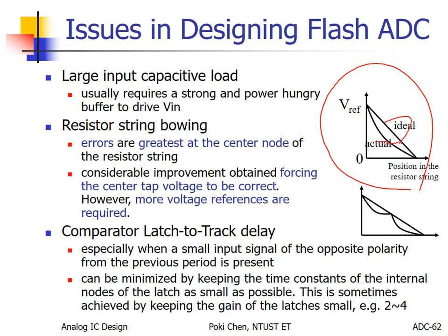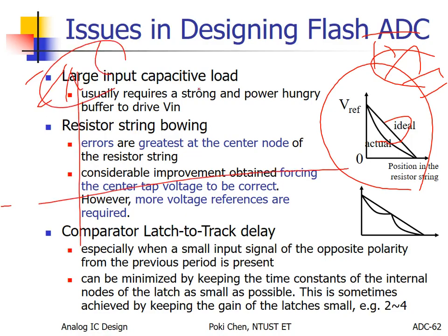If some of my students design an ADC or DAC, especially with a binary-weighted structure, you can see in the INL simulation results that you usually have the maximum in the middle. That is 50%.